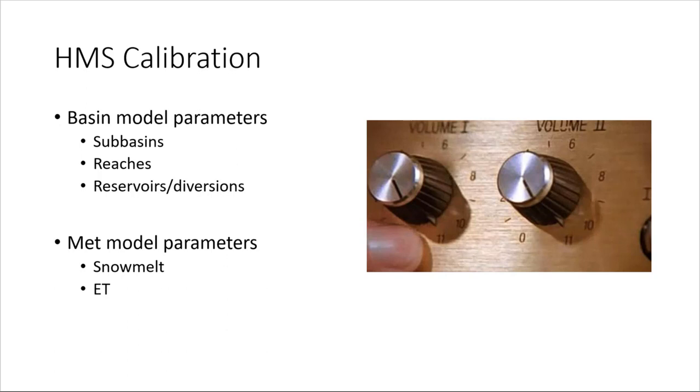Within the MET model, the most common changes are to snowmelt parameters in watersheds that need it. The temperature index method has several tunable parameters that can improve model performance not only in the explicit snowmelt and accumulation processes, but also in the resulting runoff. ET may be adjusted in a fine sense to match observations, or more coarsely to address mismatches in overall discharge volume.